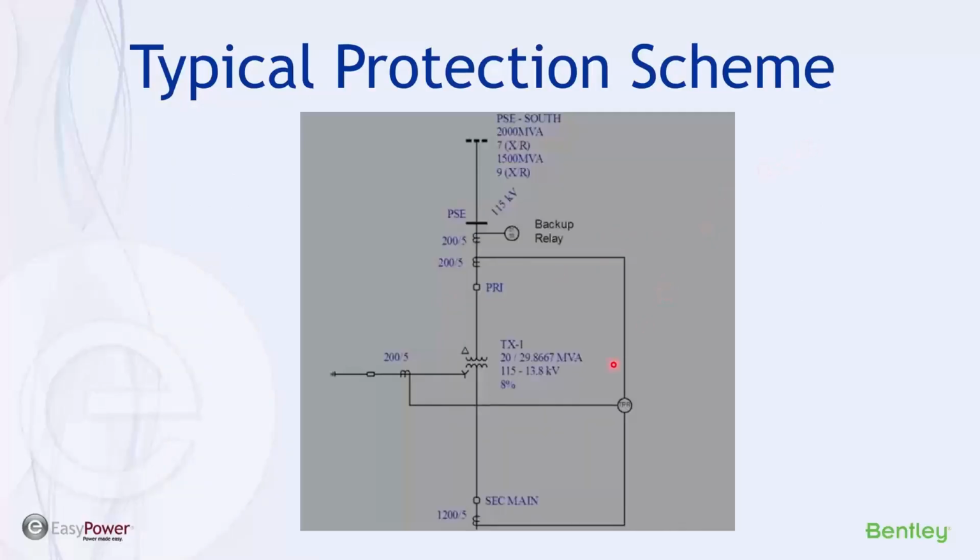A multifunction relay that can include differential, ground, phase overcurrent, and then a backup relay, again, maybe lower capabilities, looking only at overcurrent, but the ability to cover multiple types of faults within the zone.